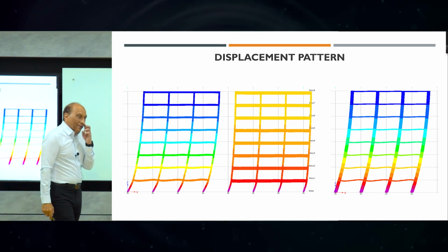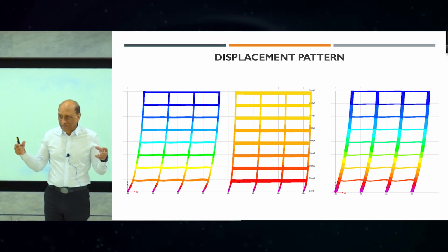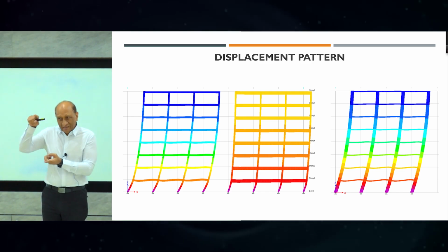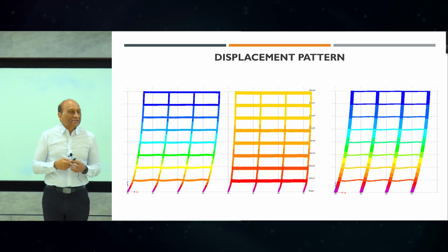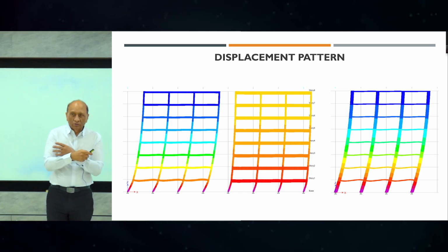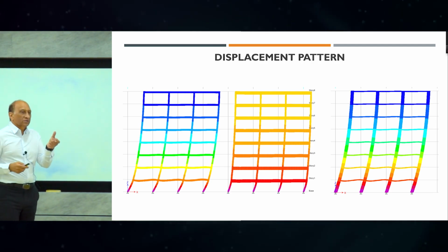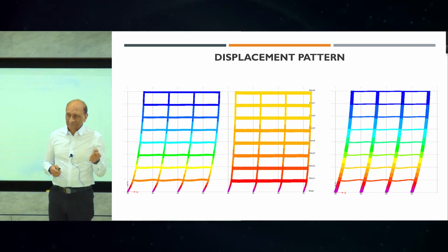So that's clear, and that is because beams are long, so their stiffness has to be increased to provide enough joint stiffness. Columns are anyway short, so if you change the size, it won't matter. So that is lesson number 1: if you want to control the lateral displacement of a building, always focus on horizontal members, not on vertical columns.